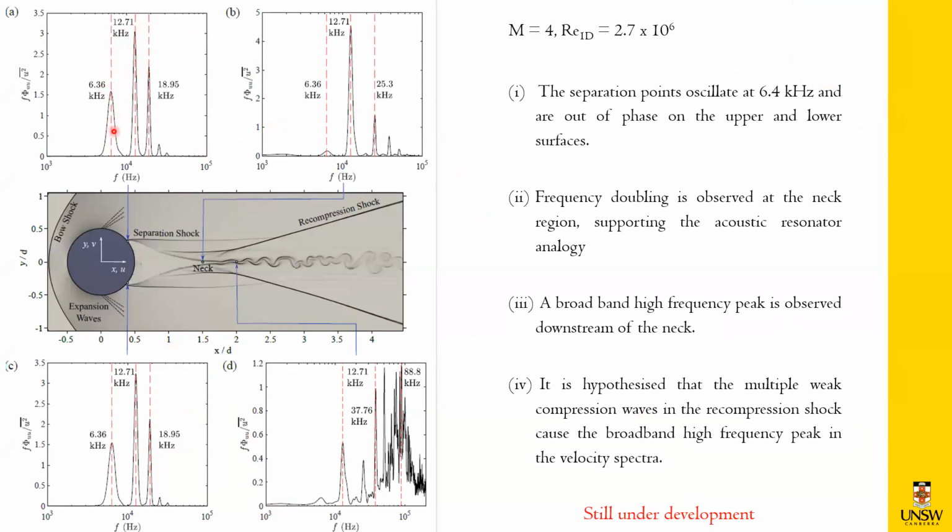My question is, are these by any means related to the free stream unsteadiness? No, in the simulations, we have a very uniform flow as the inlet. How about after the shock? You don't have any unsteadiness after the shock? No. In fact, I could play the simulation video. We see that the velocity contours are pretty constant. There are no fluctuations in velocity in the free stream, downstream of the bow shock.